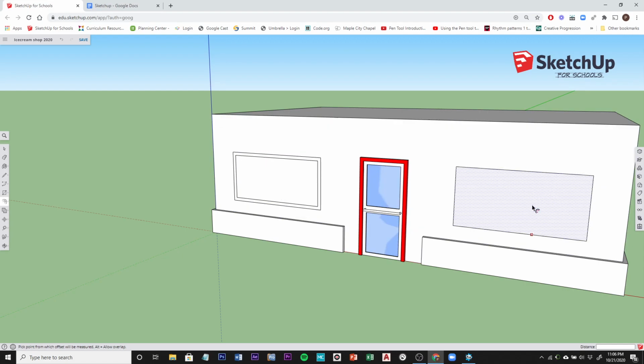We're going to do the same over here. So click on anywhere inside the shape and then drag away. And we're going to make sure that we're still on the inside and not on the outside. We're going to offset inside 3 quotation mark, enter. And again, I'll just pause for a moment here to allow you to do that step and then come back. You can pause your video. Alright, we're ready to move on.